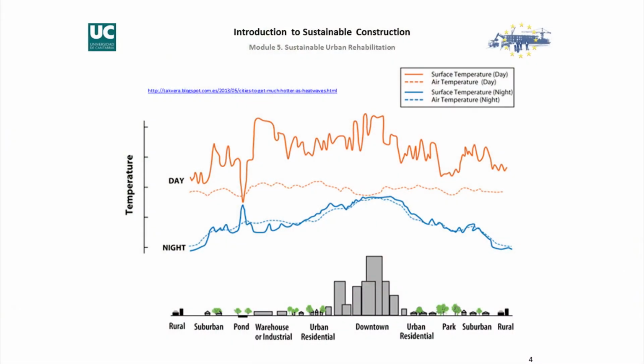incomplete water management in the cities, in conventional urbanism, is related to the heat island effect. The heat island effect is the increase of the average temperature in the city centers. The main reason is the imperviousness of the surface and the use of concrete, asphalt, and different materials that retain the solar radiation.